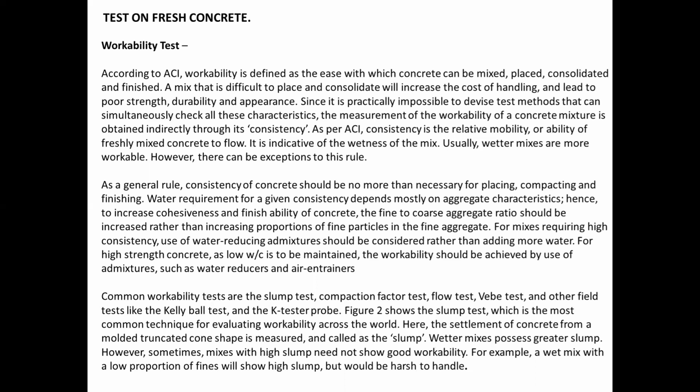Wetter mixes possess greater slump. However, sometimes mixes with high slump need not show good workability. For example, a wet mix with a low proportion of fines will show high slump, but would be harsh to work.